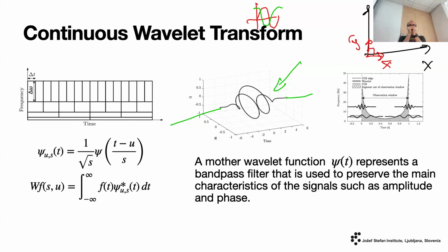So what we do is we stretch it and stamp it on our signal. And by doing so, we are taking out low frequency parts. Because we stretched it, that's why we are stamping it here. It's stretched. And if I want to find the high frequency part, I compress it and I stamp my signal and I immediately get the high frequency part. And how am I doing this stamping up and down? By this integral. This is what this integral does. Stretch it, stamp, stamp, stamp, compress it, stamp, stamp, stamp, and we actually calculate all of these points slowly.